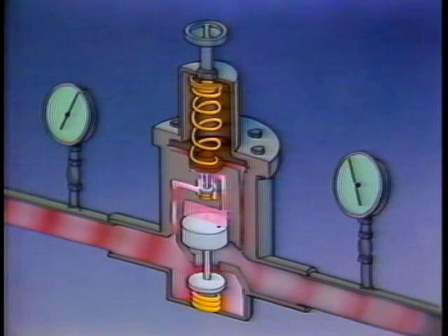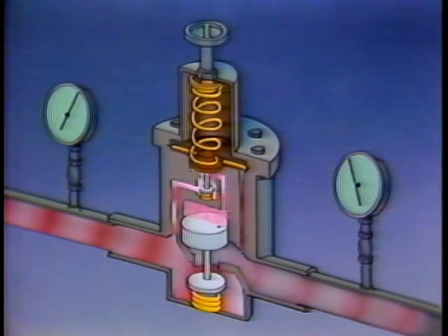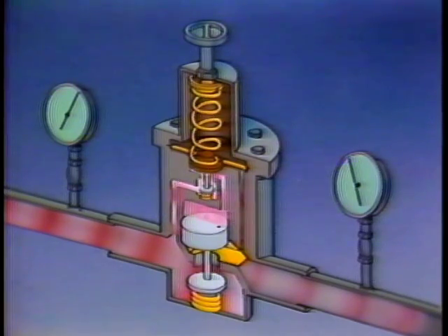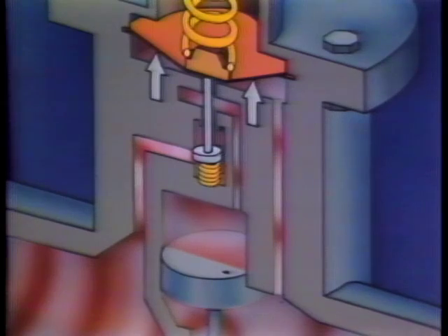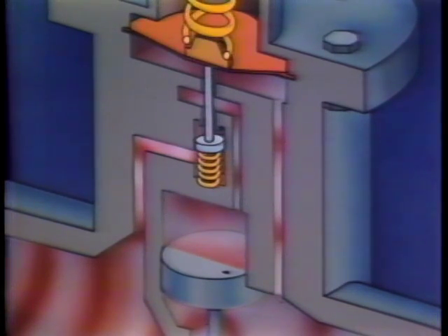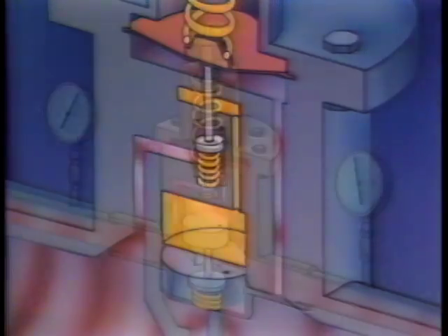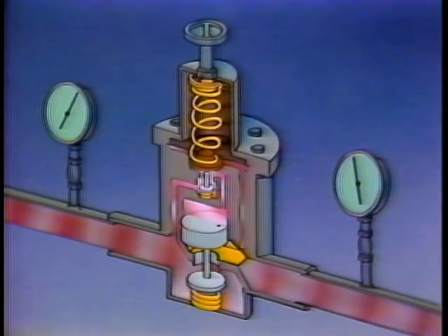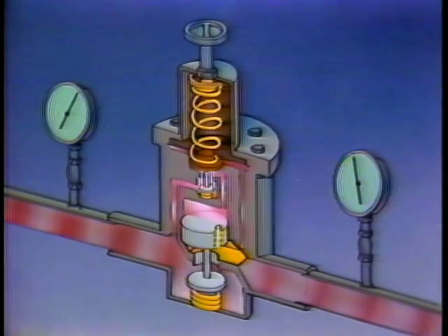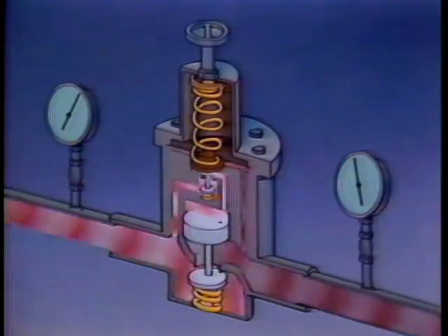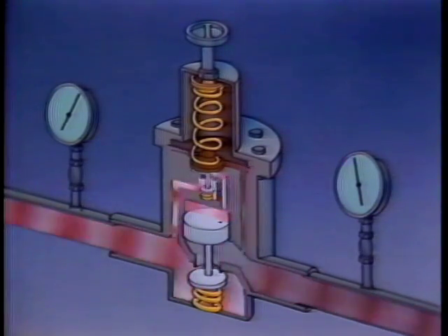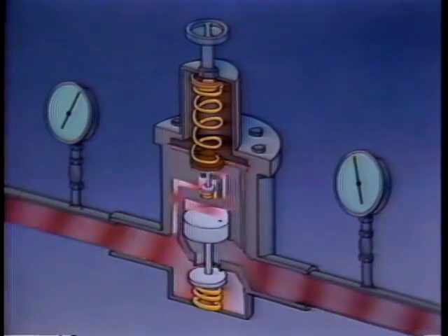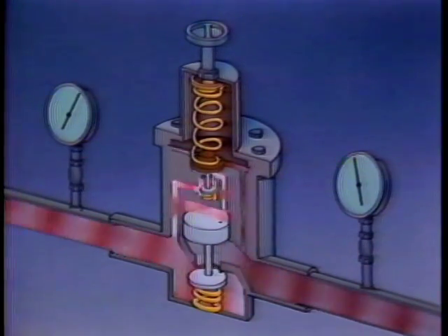At this moment, the outlet pressure reaches the bottom of both the pilot valve diaphragm and the main valve piston. Outlet pressure on the diaphragm counters the set point force, throttling the pilot valve and dropping the operator control pressure. Concurrently, outlet pressure at the bottom of the piston and the bleeding off of pressure above the piston serve to close the main valve. When outlet pressure on the diaphragm equals the set point force, the pilot valve stops moving. Flow through the pilot valve balances with the flow through the piston, and the piston stabilizes with the outlet pressure on both sides of it.